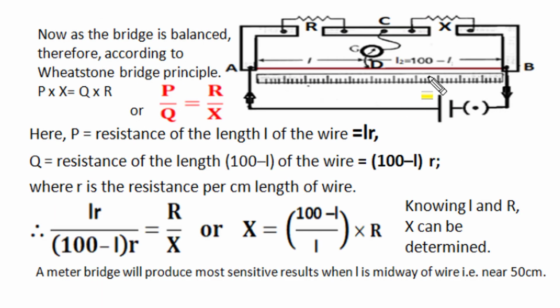As this meter bridge circuit is in balance condition, as per the Wheatstone bridge principle, in balance condition, if this sliding jockey contact divides this wire resistance into two ratio resistances P and Q, then the product of P with unknown resistance X becomes equal to the other opposite-sided resistance, the ratio resistance Q of remaining length, and R, or we can say the ratio of P to Q resistance is equal to the ratio of known resistance and unknown resistance, and